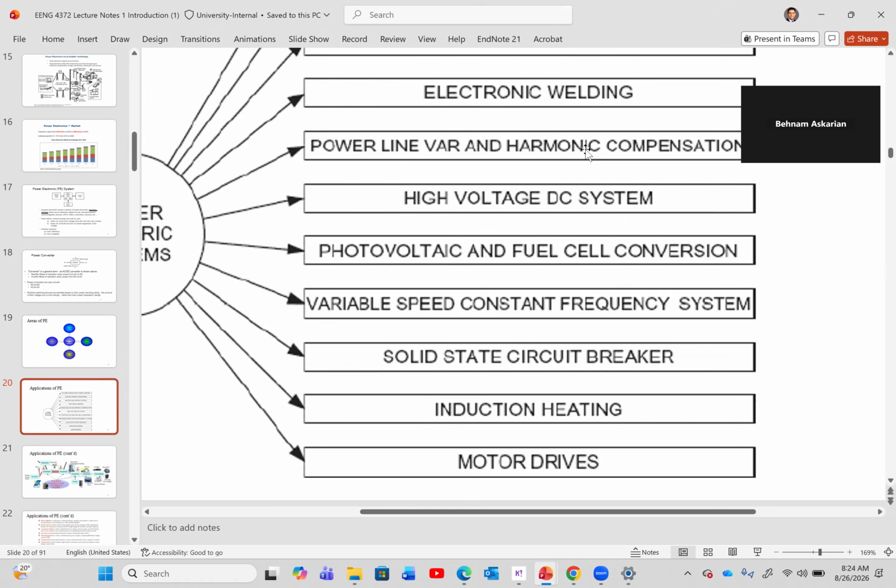Now that's useful when someone just opens the refrigerator door and closes it, because you don't need to turn on the system for 10 minutes, drop the temperature a few degrees below, and then shut it off. You can just turn it on at 20% max, cool it down to the temperature, and then just shut it off. And it has, I think, around 70, 80% power efficiency gain sometimes over the normal system. And the components will last longer.